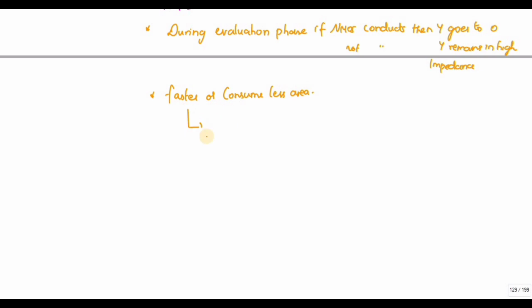Why it is faster: due to the smaller number of transistors, I have only reduced load capacitance at the output, and due to the absence of short circuit.